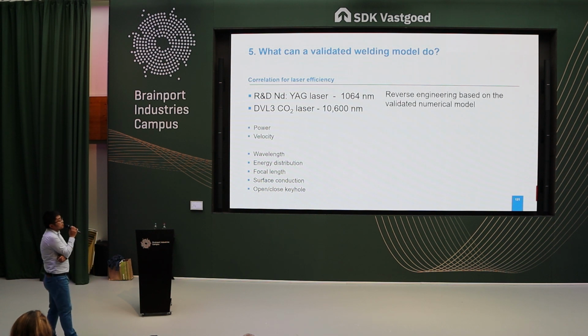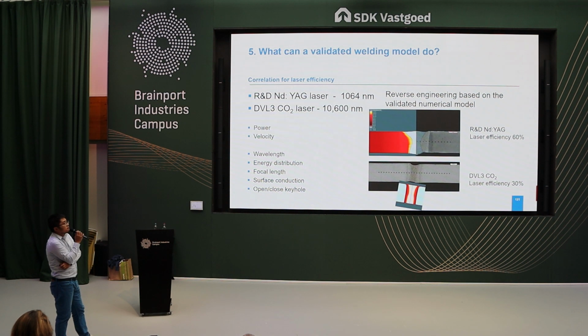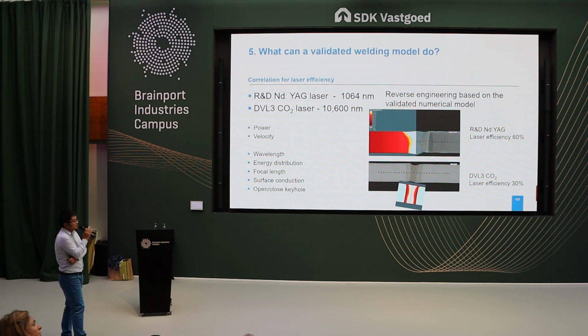So we use our model to do the reverse engineering. Then we can calibrate the efficiency of different laser machines. So from now on, any findings from R&D can directly translate to the production line based on the net heat input.